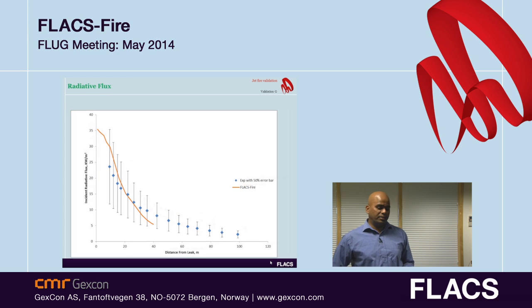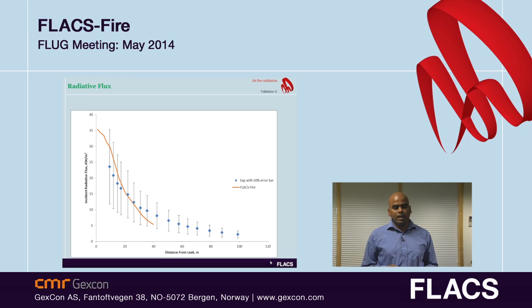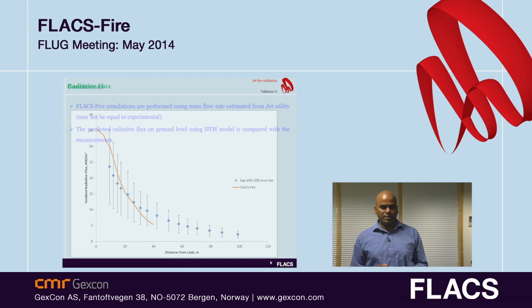So here the FLACS-Fire simulations are performed using the mass flow rate estimated from the jet utility, and the predictive capability of FLACS-Fire for the radiative flux is compared with the measurements. It agrees very well.